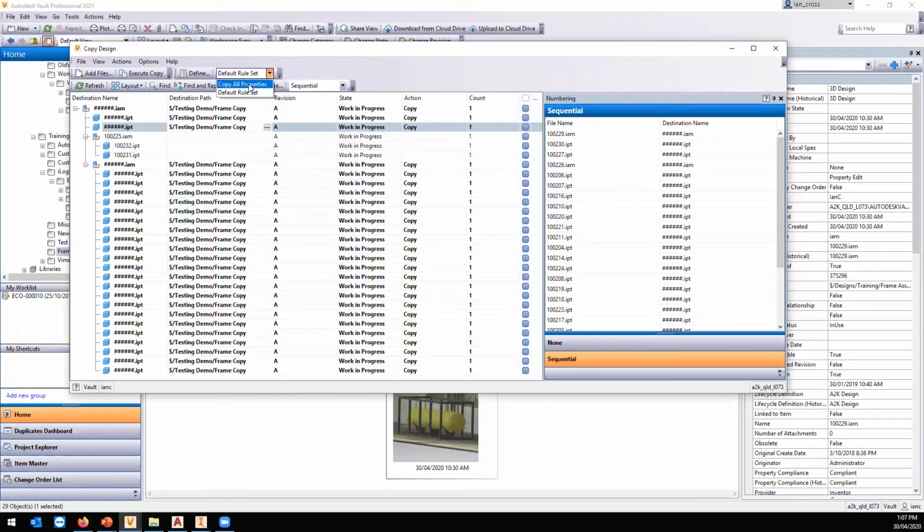My rule is going to be copy all of the properties. I want to copy all of the properties that are in the existing model to be in the new model. Part numbers, design, who designed it, costings, project numbers, all that sort of stuff. I'm going to copy it all. Now, you can define your own and only copy certain things and pick certain things and be a bit more particular. You could change the category, you could change the revision scheme, you could keep the revision scheme.